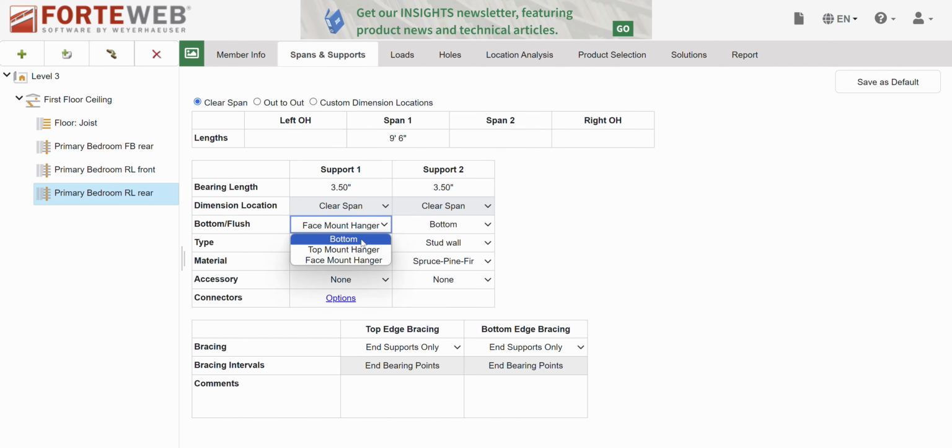Okay, we'll say 2 feet of ceiling, which is 5 and 10. I'm saying that 2 feet because there's going to be a little bit extra weight from the stuff that's attached around here to make this dormer. All right, so that's what I'm doing. It's just adding a tiny bit of weight for that. And then I am creating a point load.